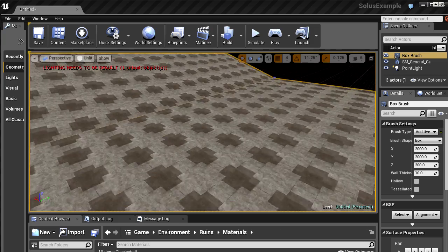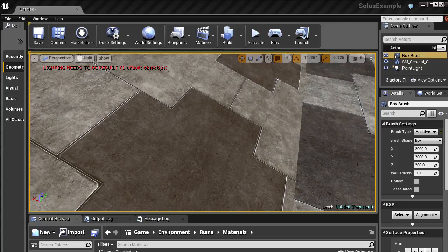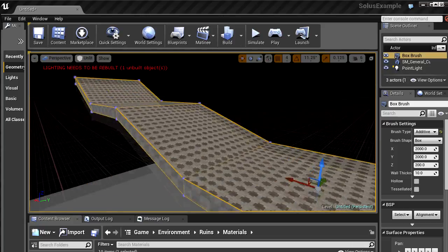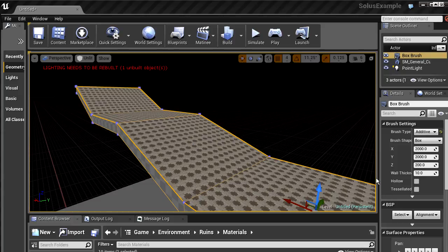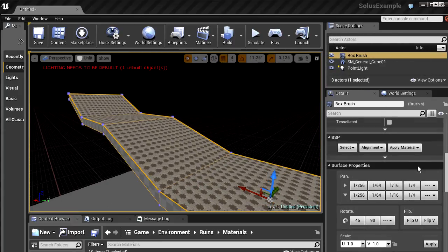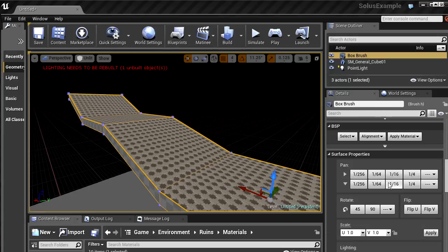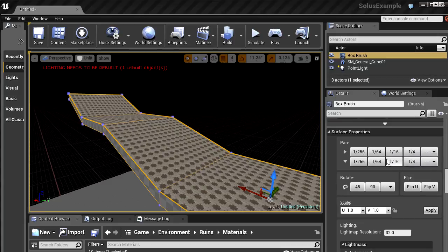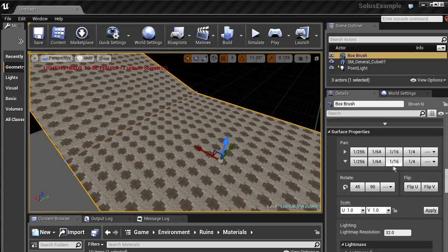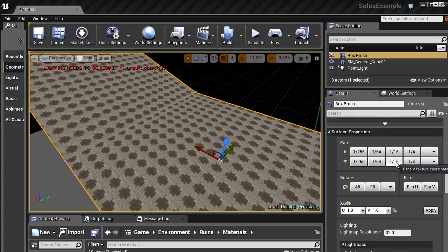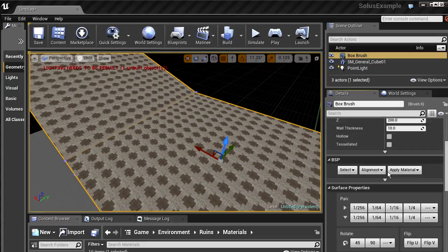We can then, because it's rather small as you can see, it's also misaligned. You can see here where the 2 surfaces meet, it doesn't align at all. So if you select the 4 tops and then look in the properties over here, at the bottom of this section, in the same place where you entered the size of it, you also got these. This allows you to move the material that's assigned to it. So if you click it, it will move. It allows you to align it with each other.